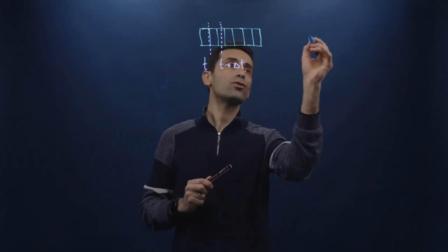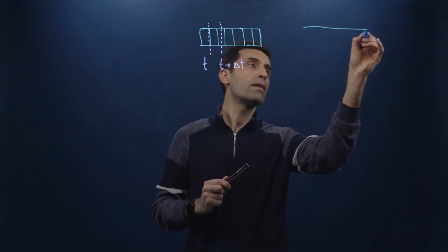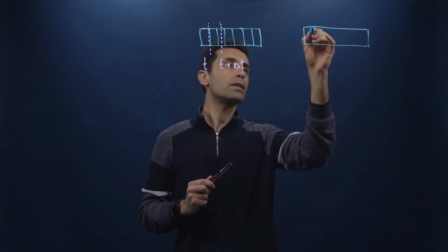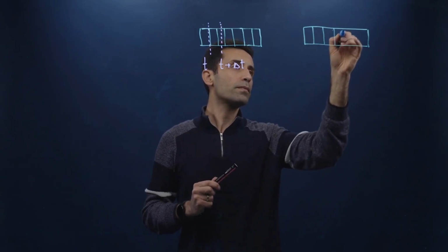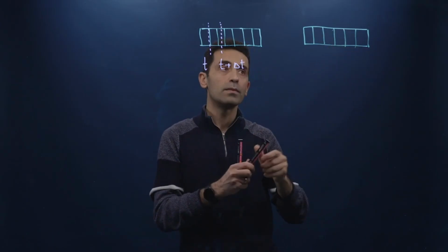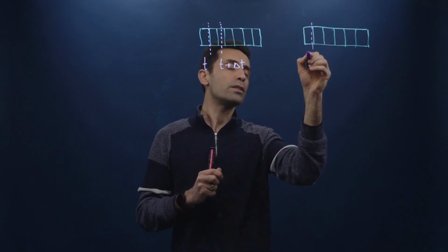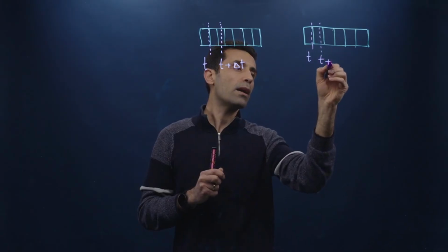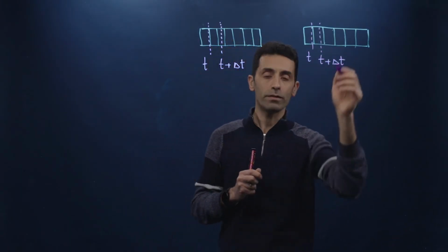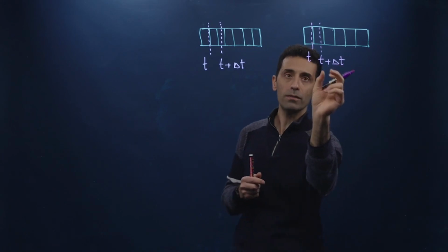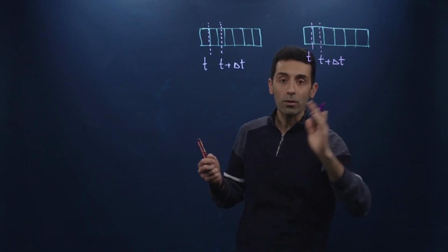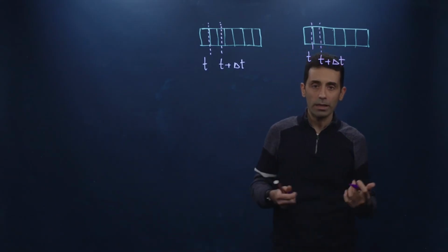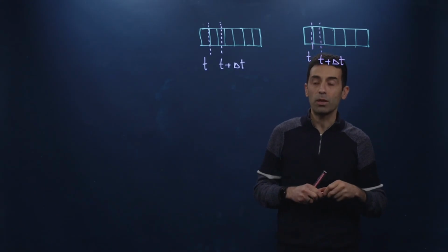Instead, this delta t should be small enough so that when this wave is traveling through the finite element model, so here we have time t, this element now is able to see the wave, yes? So delta t is now short enough for that element to see that there was a wave going through.